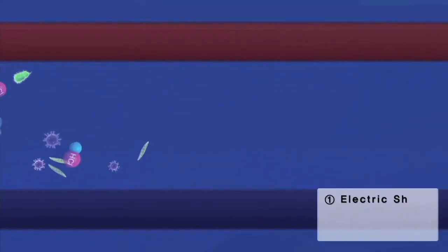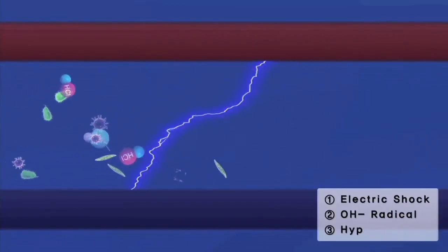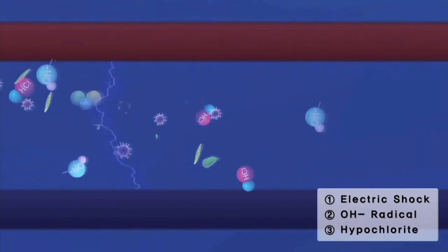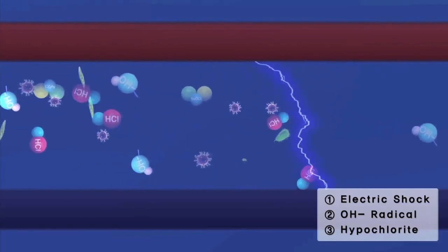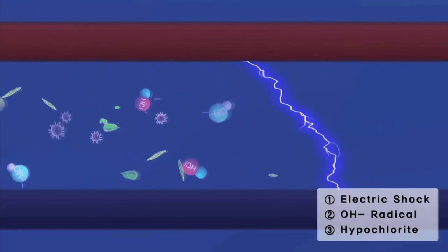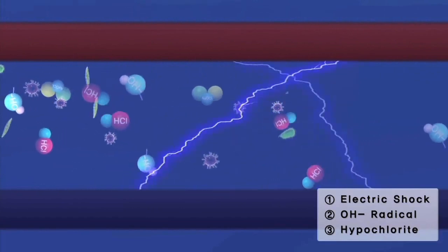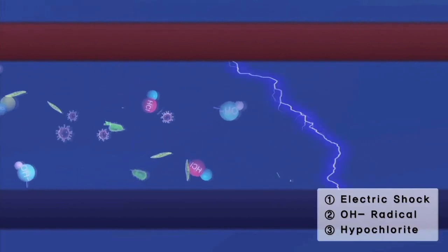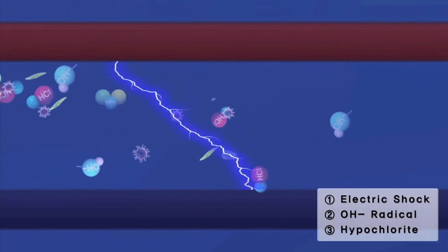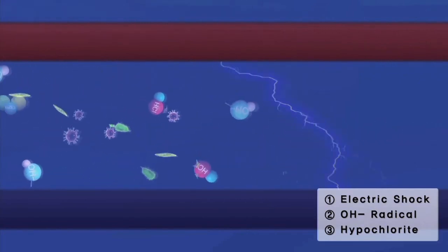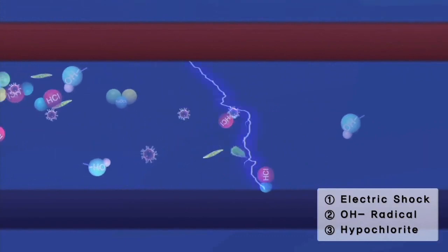1. Physical destruction of microorganisms by electric shock. 2. Oxidation by short-lived free radicals, hydroxyl radicals. 3. In situ production of 6 to 8 ppm of hypochlorite in the electrochamber unit, completely disinfecting organisms. ECS surpasses IMO D2 standards by single treatment during ballasting only, without filtration.